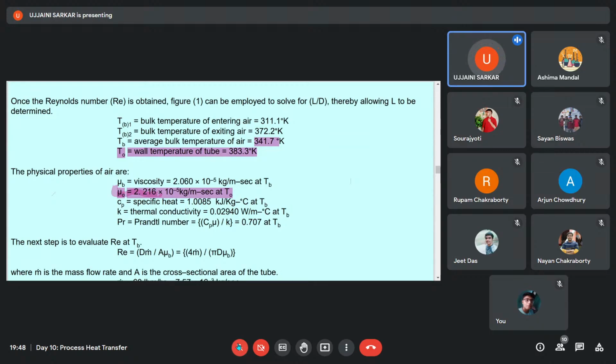We found two different viscosities, which means you have to use the Sieder-Tate equation, by bringing the viscosity correction into the picture.